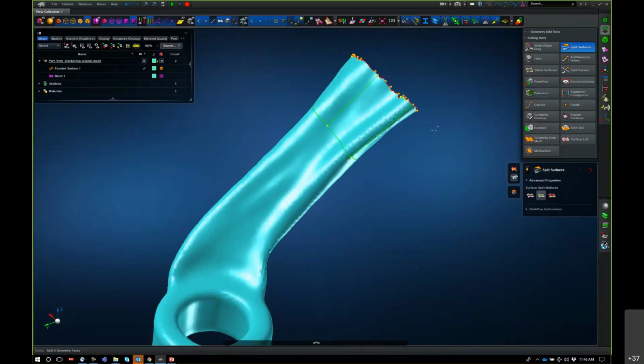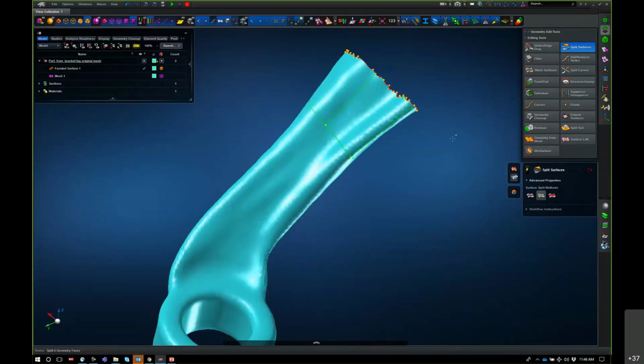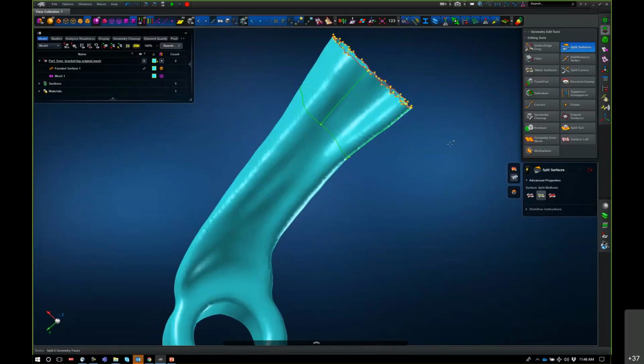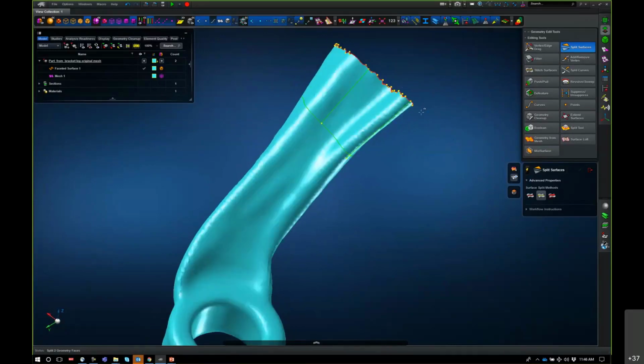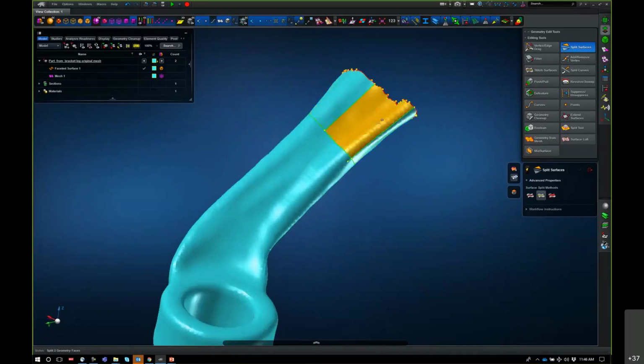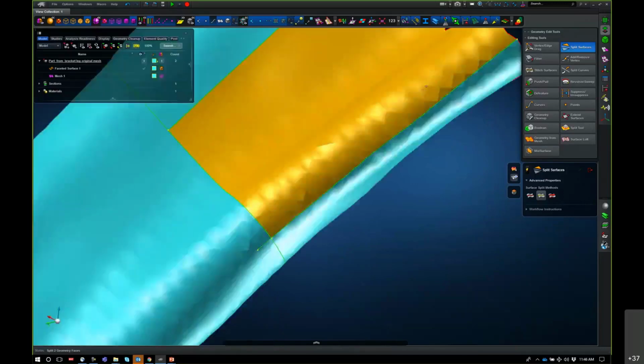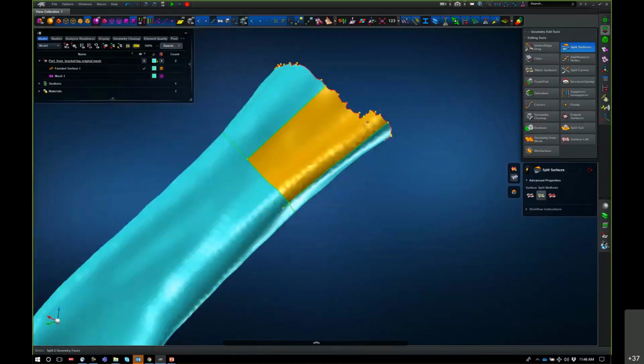So when I'm playing around with this, I usually trim this piece off and delete the end. I don't want it to work on all these little sharp teeth on the end. A really fine mesh, once again, is going to follow all the undulations in this tessellation. I'll gently break it up into a relatively coarse mesh, smooth out the facets in the process, and use that to do the conversion.